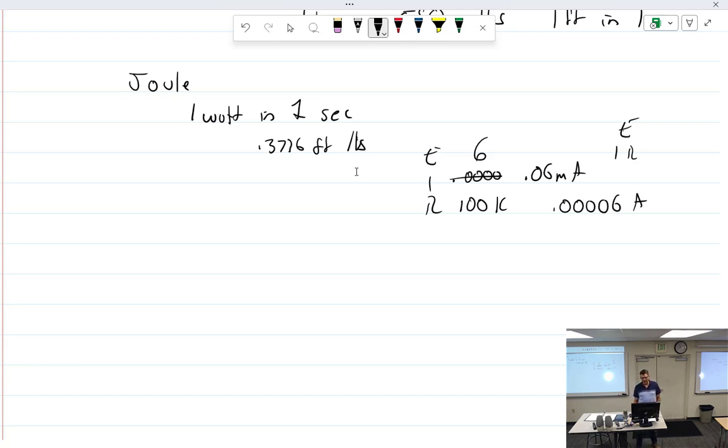If we could break through, and you get stabbed with one of these things and now you've got a resistor stuck in you, and we put some power to it, we're down to only 300 ohms at 6 volts. What do we got? 20 milliamps. That would be 4 times above the safe level. There we go. So don't do that. If you get stabbed with a resistor, don't hook it up to your 6-volt battery.